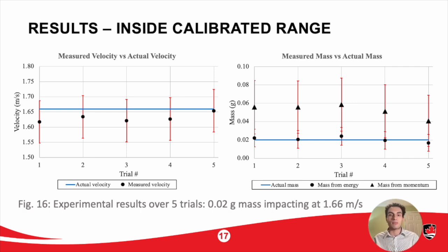The error bars on both plots were calculated through an extensive error propagation using a Gaussian uncertainty model. And so these error bars correspond to 1 sigma of that measurement uncertainty. For full details regarding all of the measurement uncertainties, such as the measurement voltage error, the measured damping ratio, measured natural frequency, and measurements in terms of the transient timings calculated for the velocity, all of those uncertainties were propagated in to calculate those error bars, and those details are in the report.